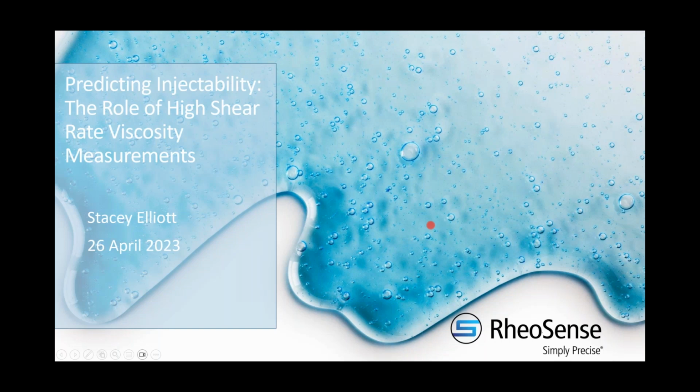So that's not something that we're predicting through calculation. That's something you'd have to obtain separately and will depend on the materials in your syringe package. And then also if you do any sort of silicone coating to minimize friction, all of those will come into play and they're not something that we're predicting here. We're focusing on what I'm calling the viscous contribution to this injection force. And this exists because the fluid is going to resist flowing through this syringe. And this resistance to flow is going to be dependent on obviously the viscosity, because viscosity is a defined property that measures the resistance of flow.